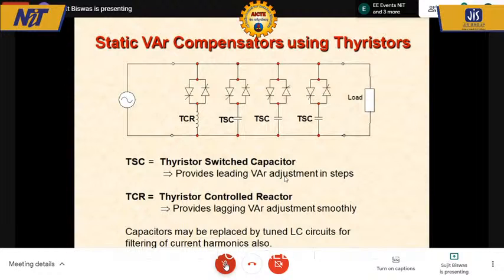So at every end, you will need additional VAR compensation and harmonic compensation with every HVDC station, because we still do not have any technology established that can replace those thyristor converters at such high voltage levels. At lower voltage levels, yes, we are replacing them using IGBTs, but it's still not implementable at such high voltage levels. But static VAR compensators using thyristors can be used because thyristors can be obtained in large voltages, they can be connected in series and so on.